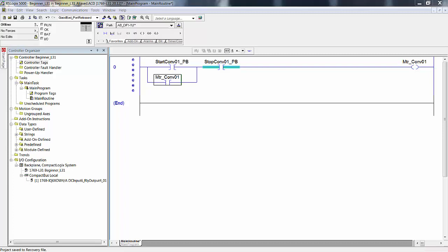If you wait until the drawing set is complete, everything is assigned. They're not going to go back and start shifting things around to add another photo eye in the best spot for it in the drawing set. Instead, they will add it to another I/O card that might be 10-15 sheets away. Now, it'll still work. That's still fine. That happens all the time.